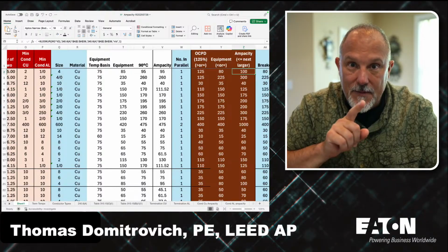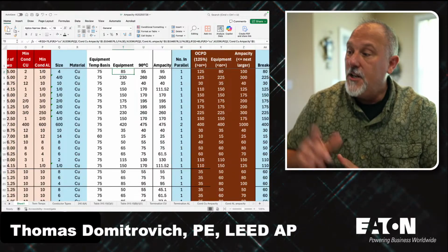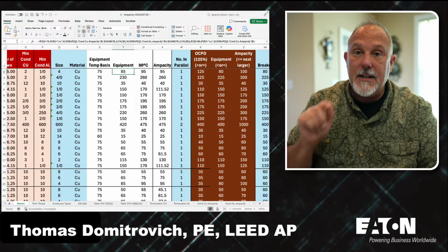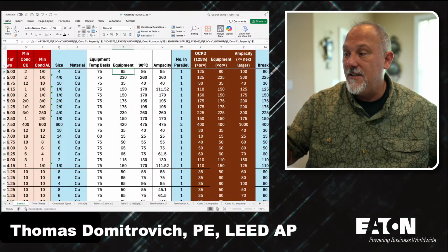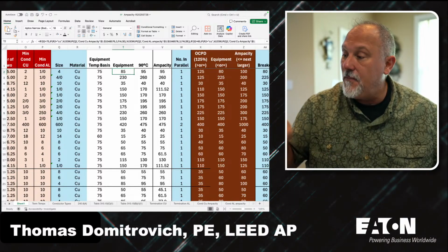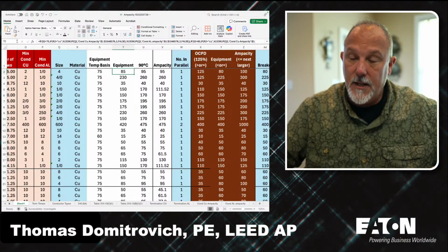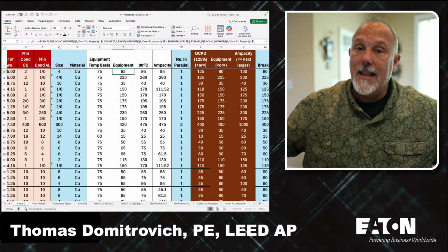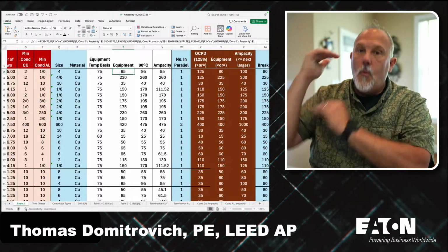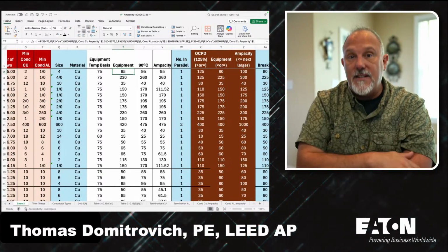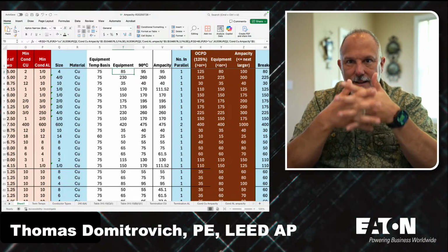What I'm not doing is meeting the equipment protection in 110.14. So in 110.14, I need a note that says, hey, you're going to have a larger overcurrent device than what 110.14 permits, which 110.14 would tell you your overcurrent device can't be greater than 85 amps. But 310 lets you do it for these specific service applications when you meet those specific criteria. It is dovetailing together.